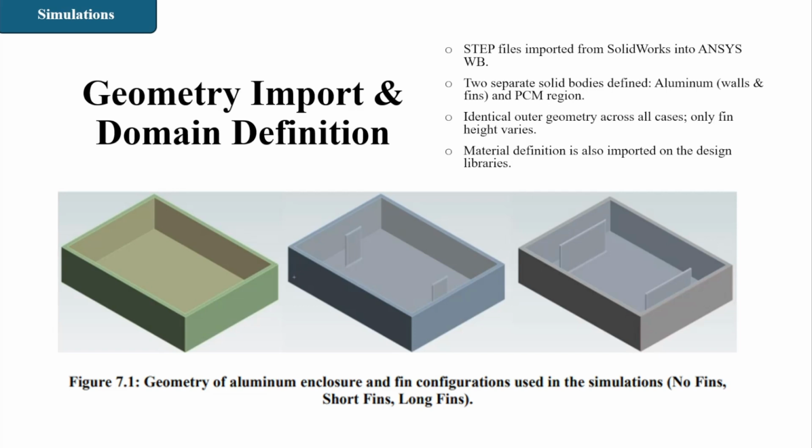In SolidWorks, this is defined as two different solid bodies, the encapsulated enclosure and what goes inside the cavity. Another important thing that was modeled here in SolidWorks is identical array geometry across all of the cases, so only fin height varies. And then the material definition is also imported on the design library side I talked to you all about.